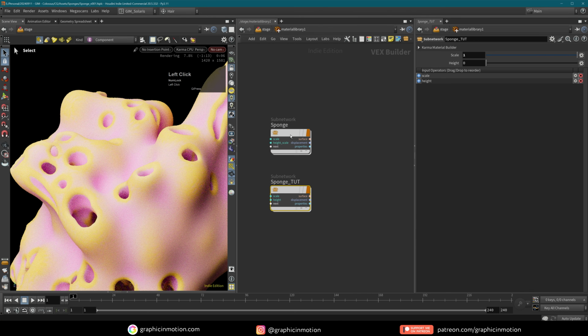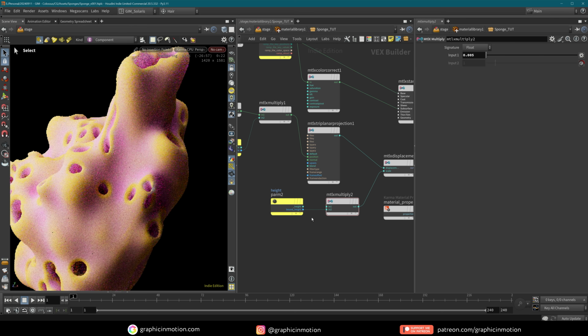And I think that this has to do with our settings here because the height is set to 0. So in my case, I want to crank this up quite a bit. So let's put 6 in here and let's see what this does. And this should now give us a result already. Oh, I know what I did. Sorry. I connected the wrong value here. So this was the mistake that I made. I connected the bound height, which of course makes absolutely no sense.